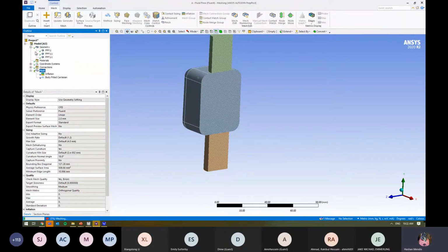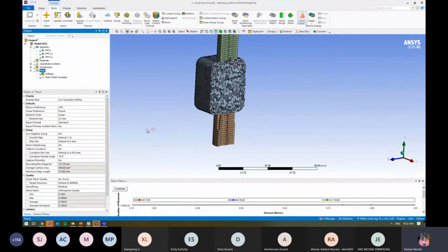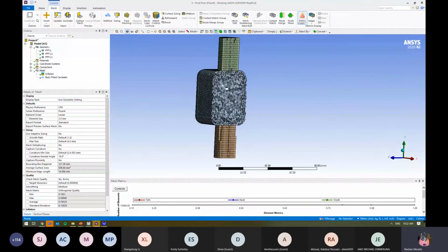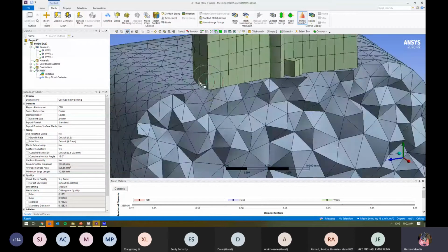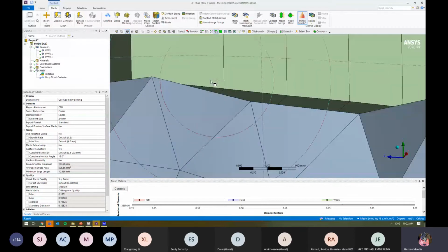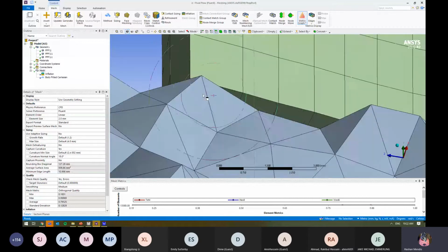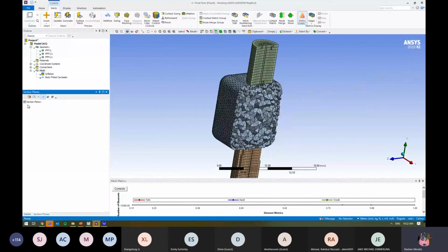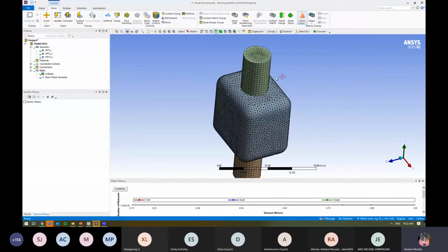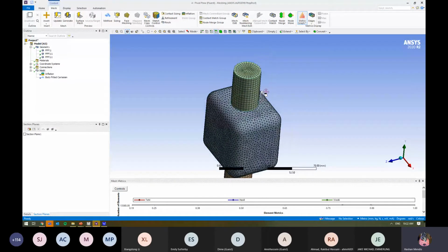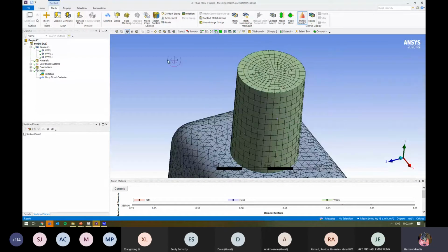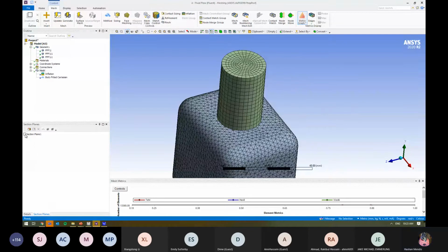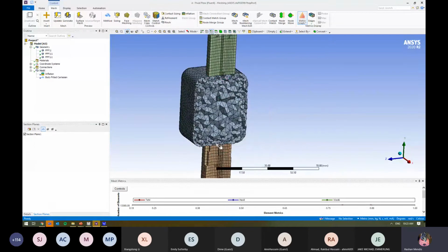What I wanted to show you here is an example where we've got 3 separate geometries. Because we haven't told it anything, they're not connected at all. You can see the interface between these 2 regions, they're not really attached whatsoever. That can sometimes be a good thing, because in this particular case, these are nice cylinders, so we can very easily specify how many elements. You can see you've got a nice swept mesh across there. I can give it inflation. I can specify how many elements I want across there. I can cut this up if I need to. And the benefit is that I know it's not going to affect the rest of my geometry.